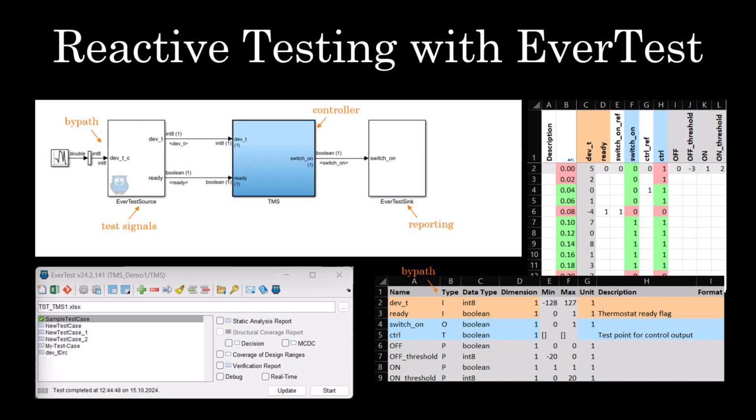Such bypass signals also allow the closed-loop simulation with a plant model. Such test scenarios enable reactive testing. It means the controller reacts on the signal provided by the plant, and the plant will be controlled by the controller. Reactive testing allows constructing all possible scenarios and simulate the behavior in virtual prototype. The results are documented in the final EverTest verification report.